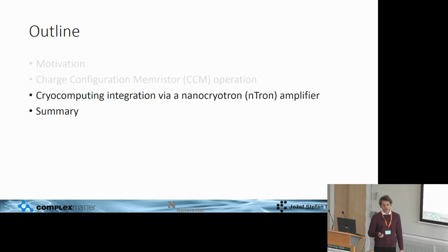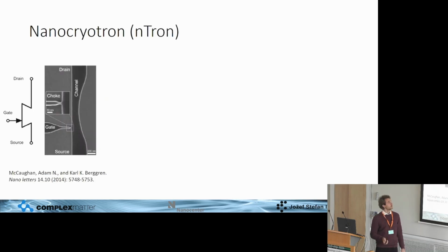Okay, great. So I've shown you this memory device briefly, how it works, some of its features, but now let's go into the second part and how we can integrate it, couple it to these SFQ circuits by using additional nanocryotron amplifiers. So first, let's take a look at what this nanocryotron even is.